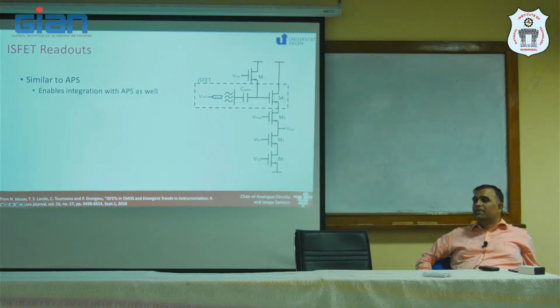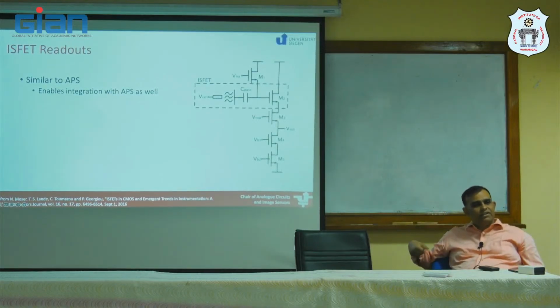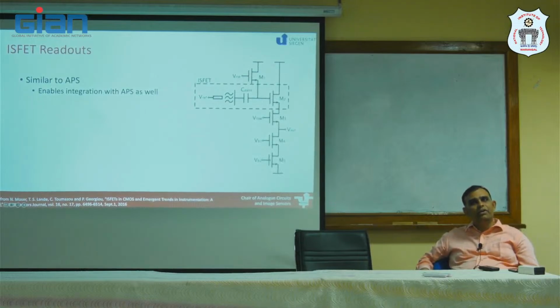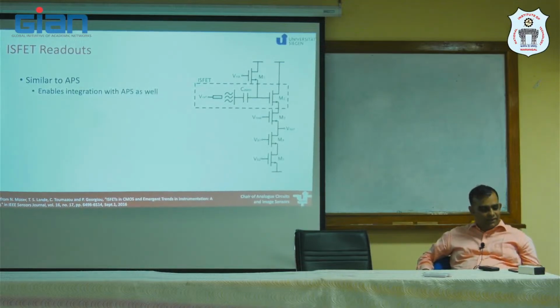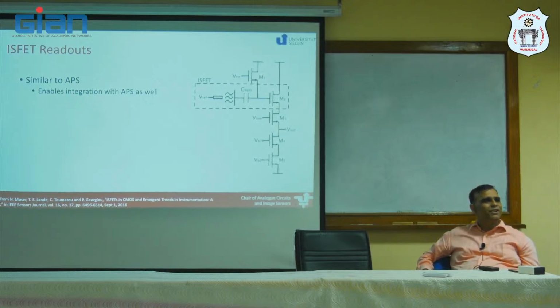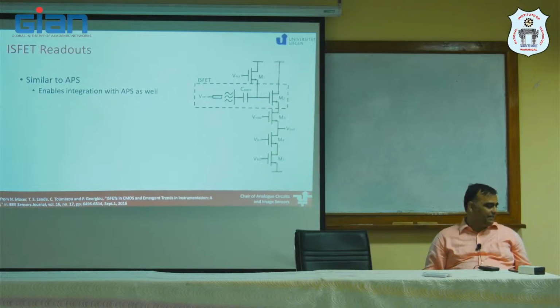These are second stage amplifiers which are being seen. These are your V bias. Remember, we applied an I bias current source. So we designed this circuit yesterday for a camera. We can use the same circuitry for a pH sensor as well. Remember, when I was talking about bolometers this morning, we could use a similar circuit in the bolometer operation as well. So the simplest amplifier, the source follower, which is taught in first year, has got a huge range of application despite only having a unity gain.